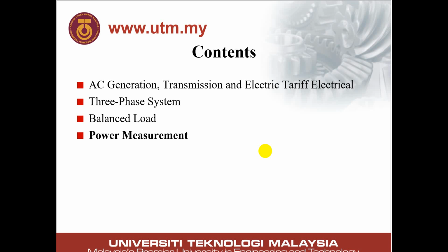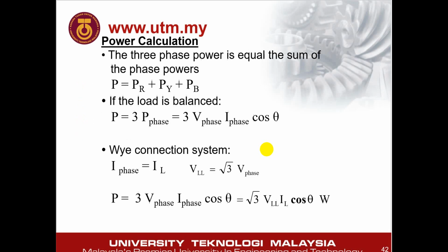So what is the difference between single phase power measurement and three phase power measurement? Because your subject is only focused on balanced load, this is much easier. Why? Because basically you just multiply by 3. If you calculate the power, you just multiply by 3. You get the total power of the three phase system.